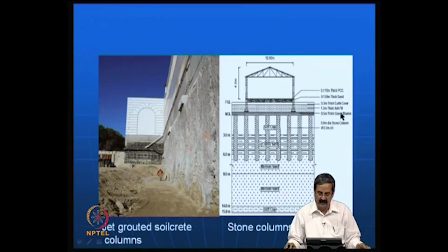So, this is another example for a containment yard in which you have stone columns here. Stone columns are nothing but, say for example, the area here is soft soil, here the soil is clayey sand, this is a medium sand here, medium and stiff clay here. So, this is the floor level and it is all resting on soft soil. So, we try to put the foundation slab of this particular material, it is called a gravel blanket we are putting here, and then we come out with some design in the form of stone columns here.